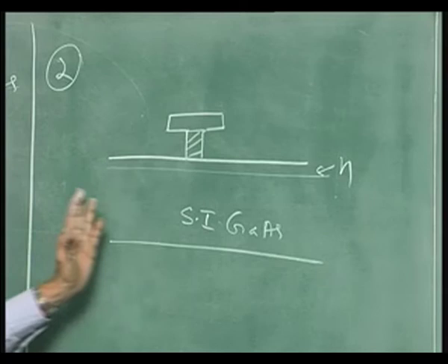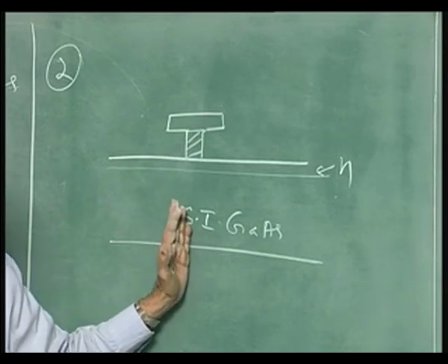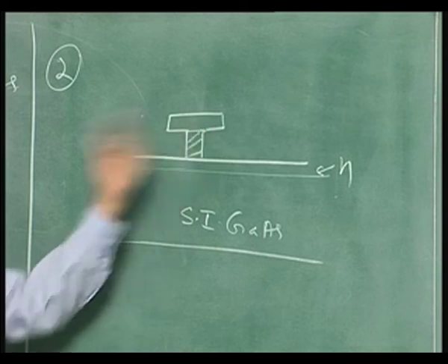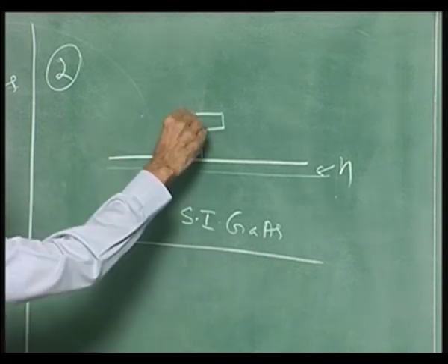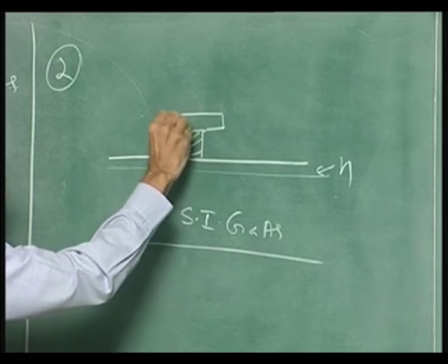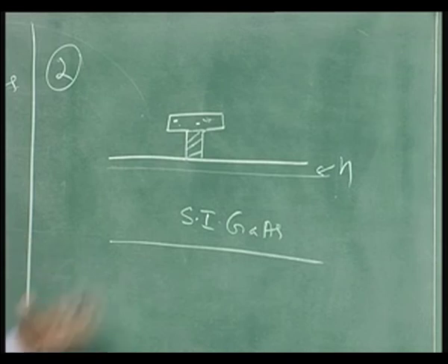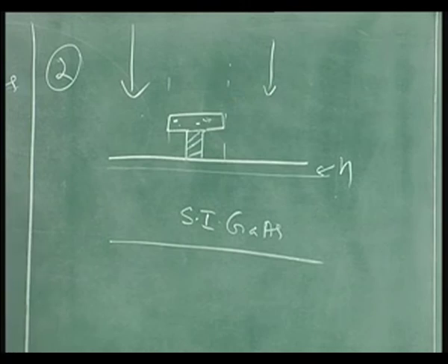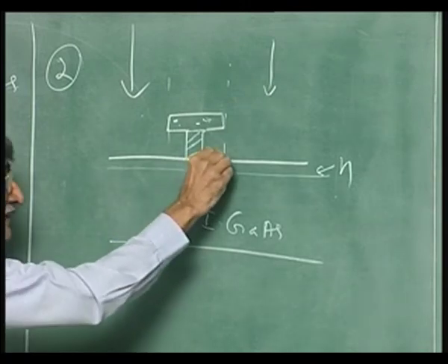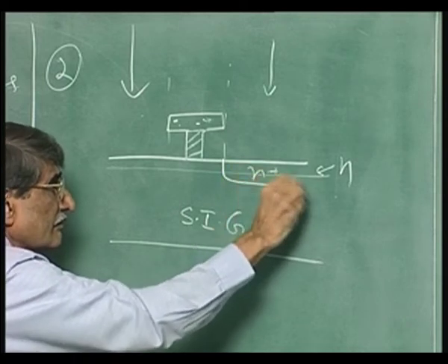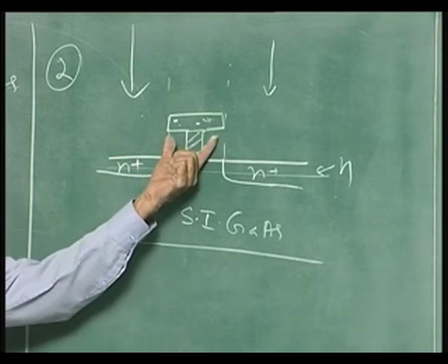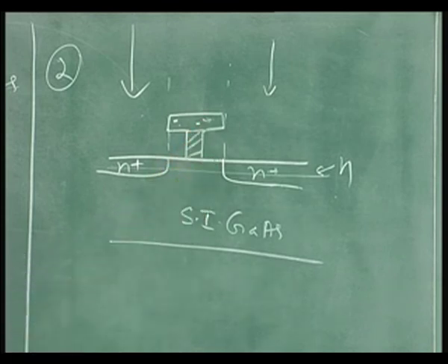So, what we do is we go back to this type of structure, okay. And if I have a structure like this, how do you do that? What you do is, let us see, supposing you realize this type of structure, you can use this as the tungsten, this is another material, this is a mask. Okay. Let us take this structure that is realizable, and then what do you do? You implant. An implant is vertically going down, therefore, implantation takes place here. Because this is shadowing that. Underneath that, there will not be implantation. It is like putting that mask implant on both.